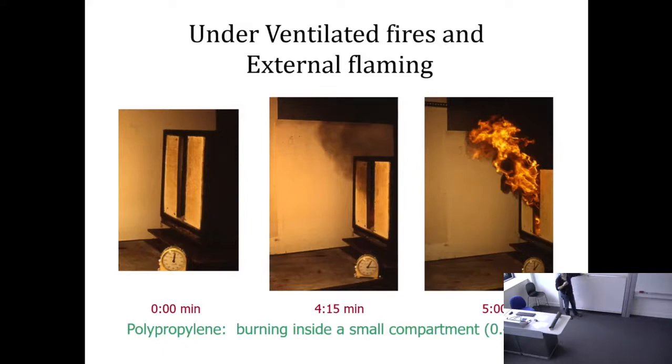When you reach flashover, which is the largest fire that can happen within a compartment, it will not be able to grow any farther. The fire runs out of oxygen. The amount of oxygen going through the bottom part of the vent is not enough to sustain the combustion process inside. And actually, the excess fuel that has been pyrolyzed, but doesn't have enough oxygen, leaves the compartment to find oxygen. And then you have the phenomenon called external flaming, which is when you see flames coming out of the compartment. That is a sign of flashover.